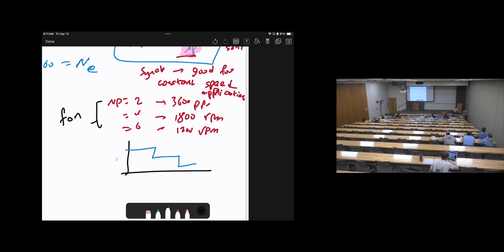And also they modified it into another updated, better version called the brushless DC motor. I think you might have heard of it. A brushless DC motor is actually a three-phase AC synchronous motor. Why is it called DC? Why is it called brushless? Because they made some modifications. They made it very simple, so it looks like DC. The way you control it is very similar to the way you control a DC motor.